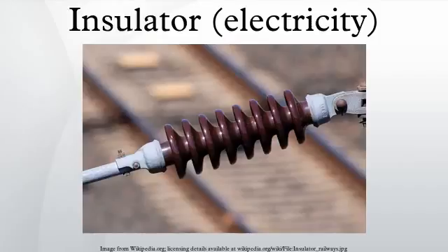Live front switchboards up to the early part of the 20th century were made of slate or marble. Some high-voltage equipment is designed to operate within a high-pressure insulating gas such as sulfur hexafluoride. Insulation materials that perform well at power and low frequencies may be unsatisfactory at radio frequency, due to heating from excessive dielectric dissipation.